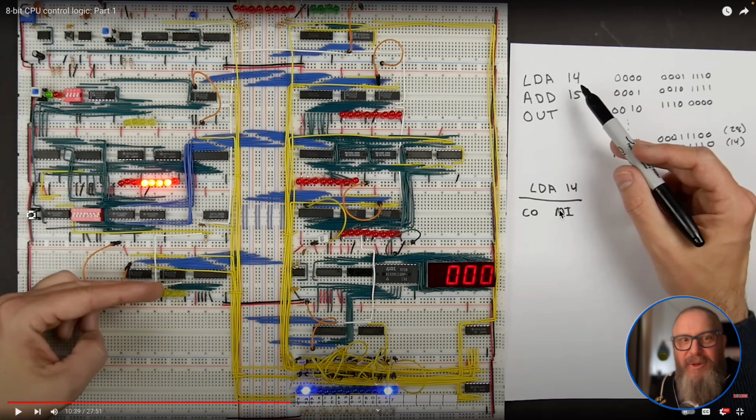So this is called microcode. Each opcode, this is why it takes a couple cycles to have a CPU actually run an instruction, because this is the microcode. There are little programs that run for this LDA. There's a little program that runs in the control unit to do what LDA does. It doesn't just do one thing. It could do a whole bunch of things. It could take 10 clock cycles, 2, 5, 8. It depends on what you're doing, right?